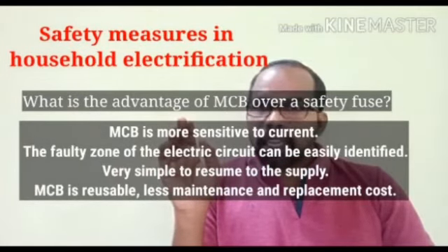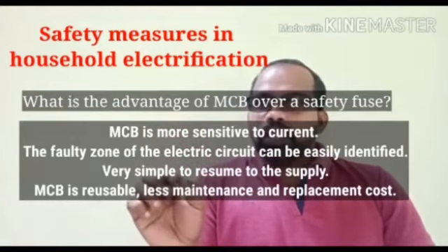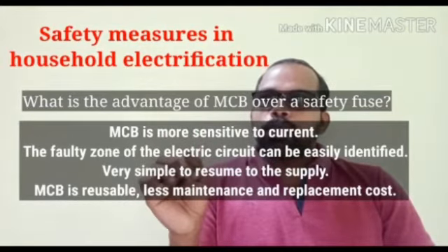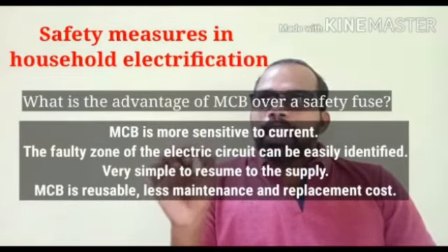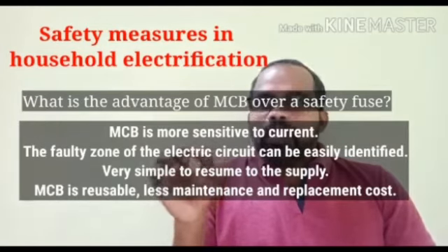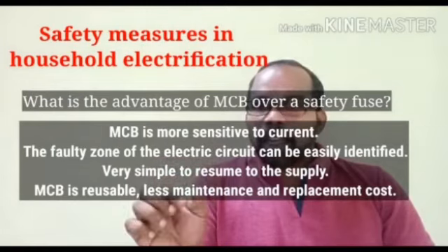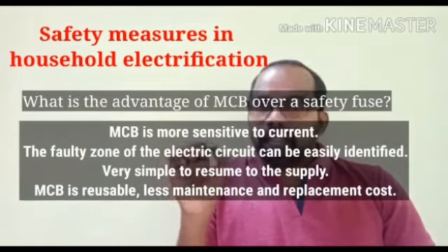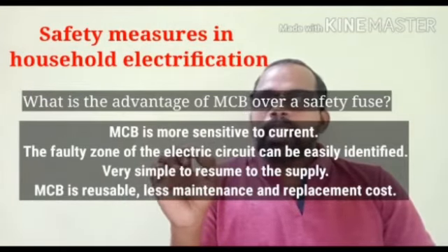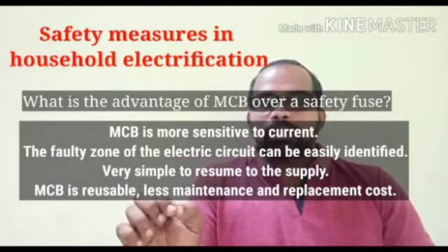I will repeat once again. MCB is more sensitive to current than a fuse. With MCB, we can easily identify the faulty zone and it is very simple to resume the supply. And MCB is reusable and hence it has less maintenance and replacement cost.